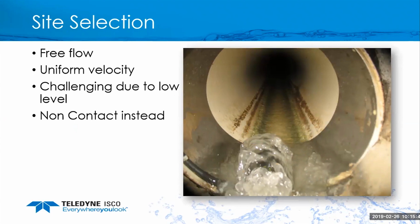Another application, this is a free flow application again. We have uniform flow going, or flow and velocity going through the pipe. However, the challenge is that we have really low level in this application, and so the water is just tumbling over the top of this area velocity sensor. It doesn't necessarily mean it's a bad application, but it depends on what you're looking for. If you're only concerned about the high flows, and you know the water depth is going to get up to 4 inches or 6 inches in this pipe, and you're not concerned about low flow, you could put an in-pipe area velocity sensor in there and be just fine. Or the alternative is to use a non-contact laser flow sensor, which would be able to read the lower levels and velocities.